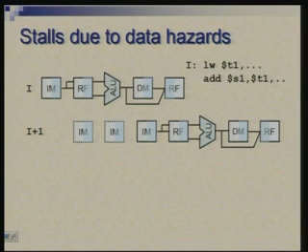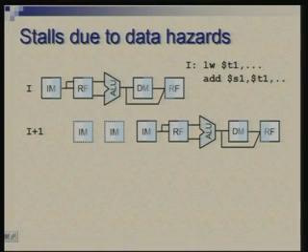So, then I keep a clock period of 2 nanoseconds, and within these 2 nanoseconds, as far as the register file is concerned, I can spend the first half of the cycle or 1 nanosecond in writing and the later half in reading. Okay. So, that gives me a little advantage here, and otherwise I would have to delay it by 3 cycles, and I am now managing by a delay of just 2 cycles. Okay. So, if you do not do that, then there will be more delay.